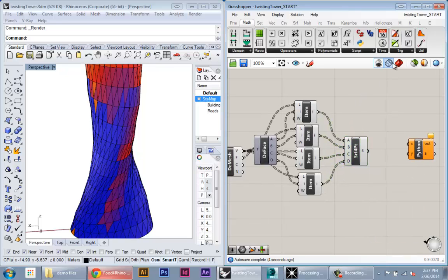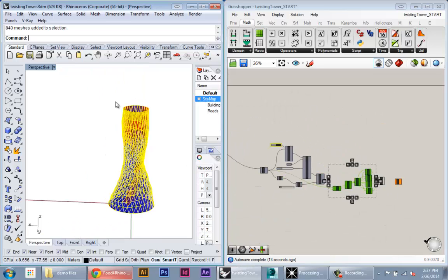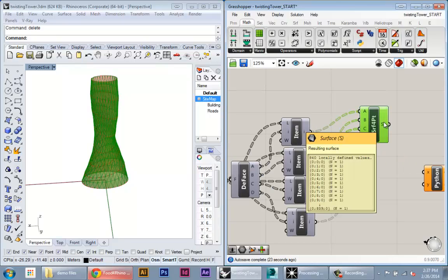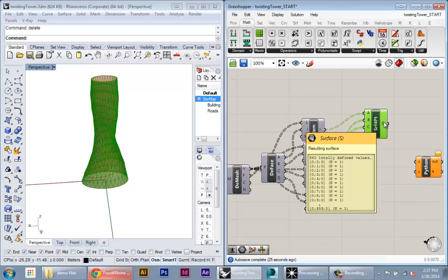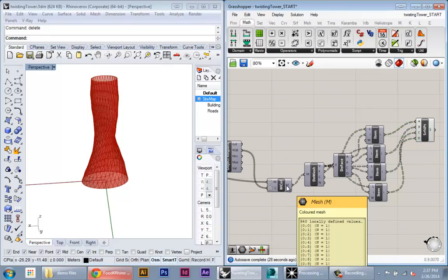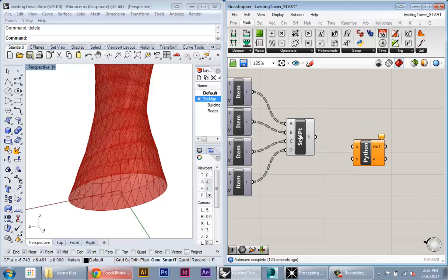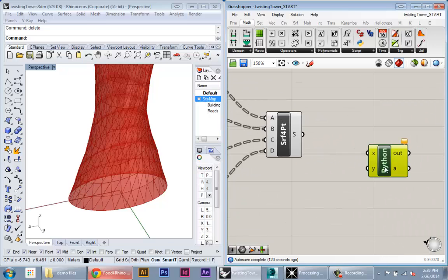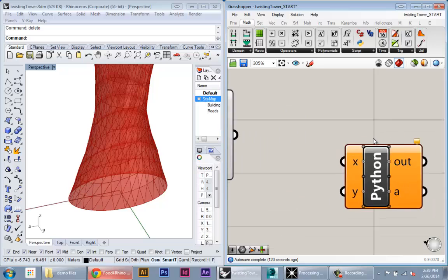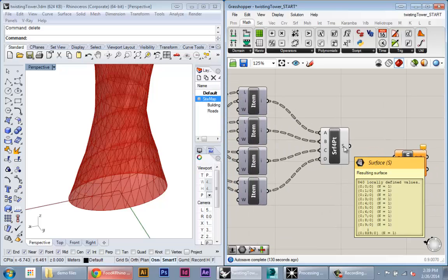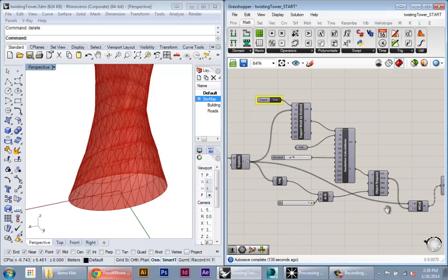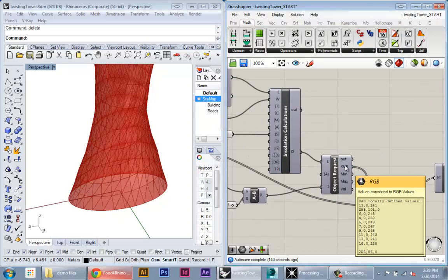Now, I'll delete this Rhino geometry that I baked. So now we have all of those meshes back as surfaces, and now they're all on different branches of the tree, but there's 840 surfaces coming from 840 meshes. Once we have these surfaces, basically we have all the inputs we need into our Python node to start to bake this geometry with material properties. We have 840 surfaces we want to bake, and from the Ecotect analysis, we have 840 colors that we want to use for those materials.